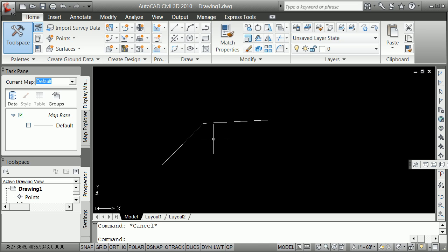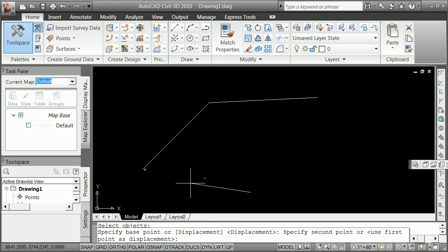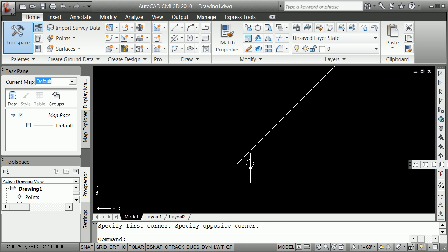and we're now just going to make a pipe here, then we'll try it next time with a road. So I'm going to do a circle here. I'll make my circle pretty big, go across here and make it a circle of maybe 4 foot in radius. It's kind of tiny, but I'm going to move that really close by to here, and we're going to then look at what the problems would be and what Civil 3D gets around. But very often you could take and move this thing, turn it, and get it to sweep through so it was actually perpendicular to that 3D polyline, to the axis of that 3D polyline. That 3D polyline could either be the spring line of a pipe or the invert line. The spring line is the center line of the pipe.